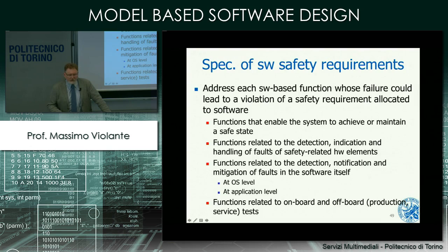Then, do we do fault detection in software? Let's say we recognize that we have to deal with errors in the communication channel. How do we do that? Do we have a function that is able to keep track of how long ago we last received something on the CAN network, for example? Let's say we have sensors. Do we do some range check on the provided values from the sensor to verify whether the sensor provided something, and if the value provided is within the working range of the sensor?